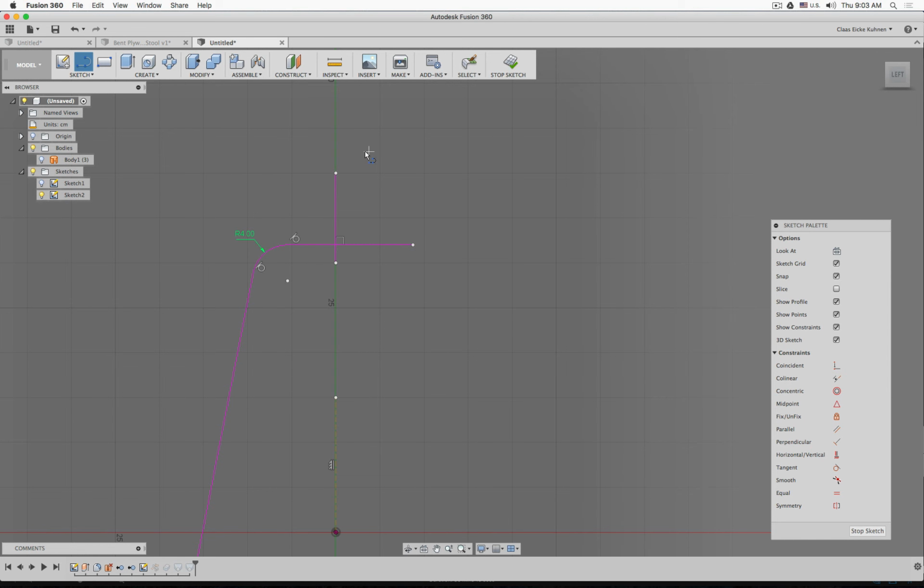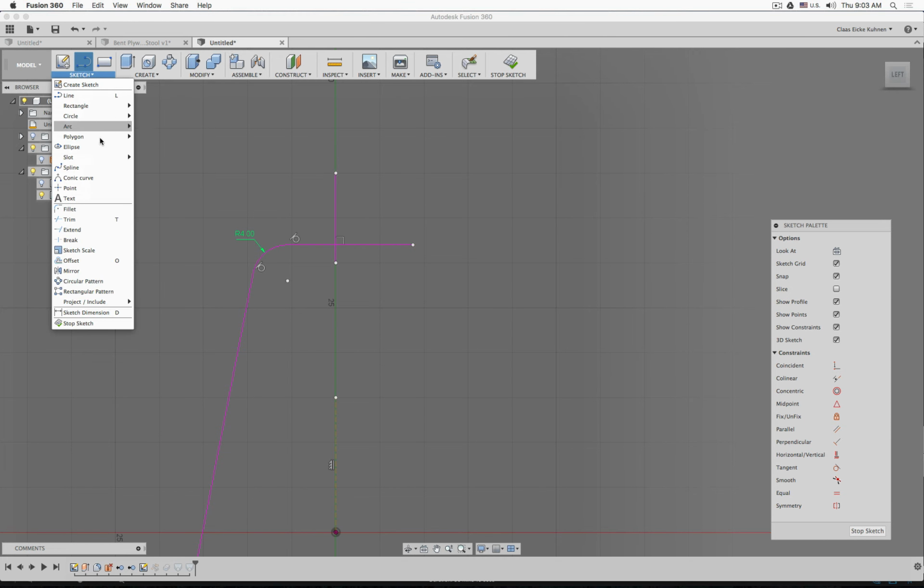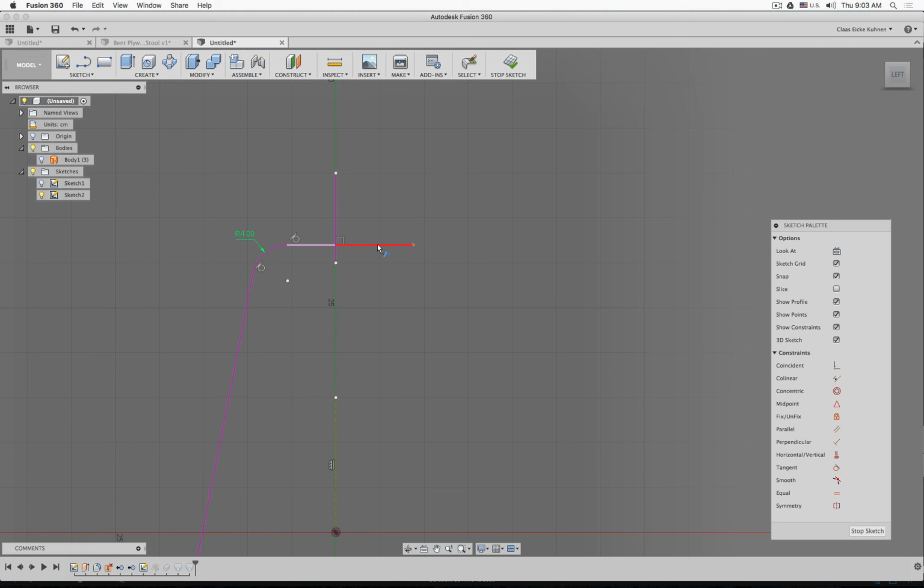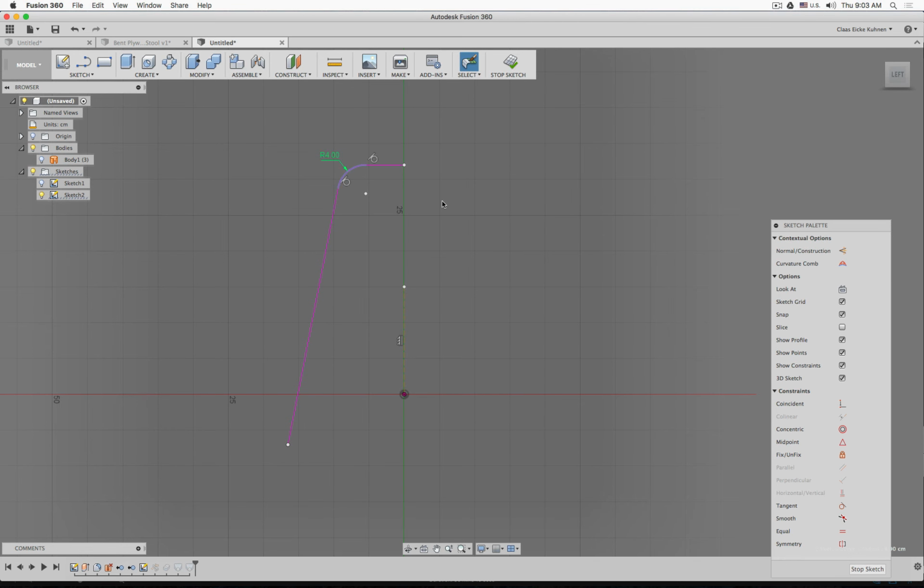I'm just introducing some drawing tools for you. And then we can trim this off because we drew this line. Trim it, press escape, select this line, delete it. Okay, good. Now here is my radius. And again, this is not what I want, so I will delete it. So similar to the surface where I used the fillet to simply create an even opening, I do the same here in the sketch and then just delete it.